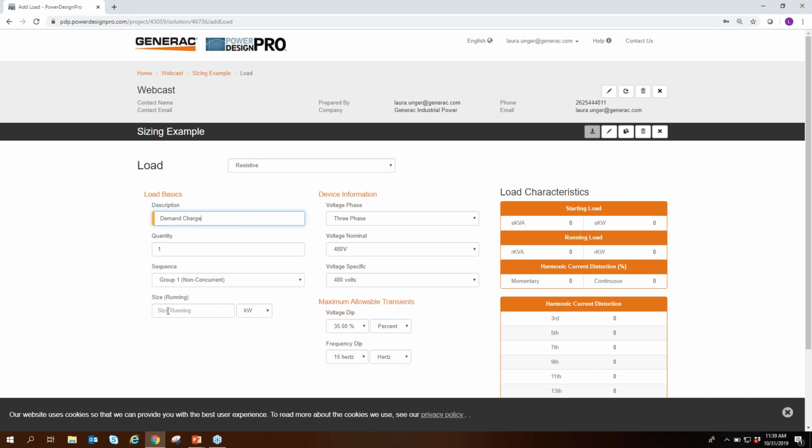And if I want to put in 200, I could just simply enter 200 kW like this. But if I do that, I'm actually creating kind of a false condition. It's basically bringing 200 kilowatts of load on all at one time. You can see the 200 kW start hit here. That's probably not what's going to happen. You're going to initially close in with the transfer switch, and you're going to have some lighting, and then the building's naturally going to come back to life, HVAC, any of the larger loads in the building.